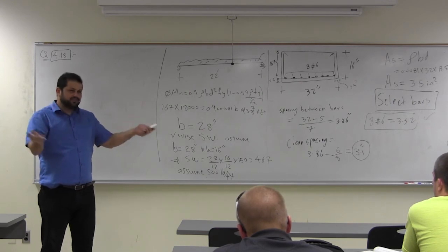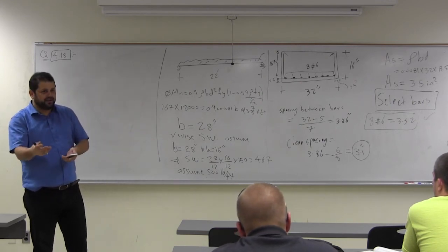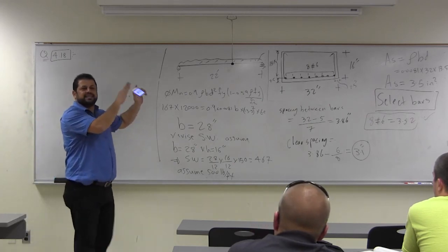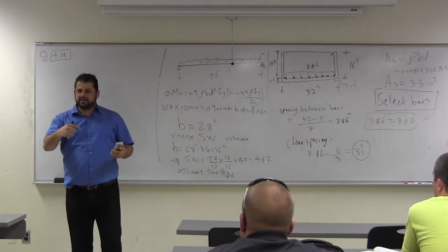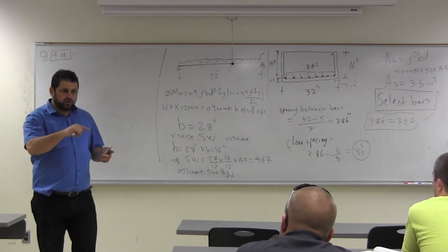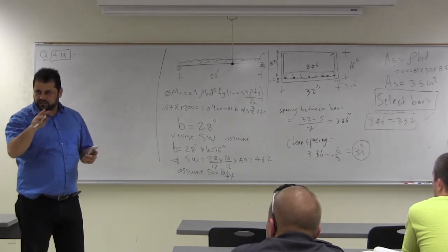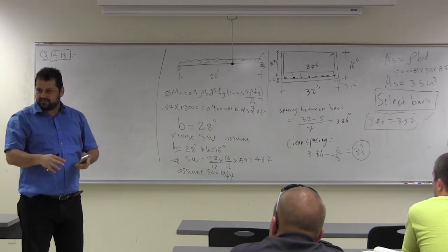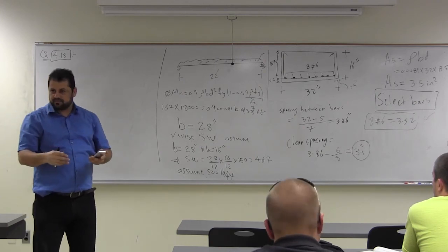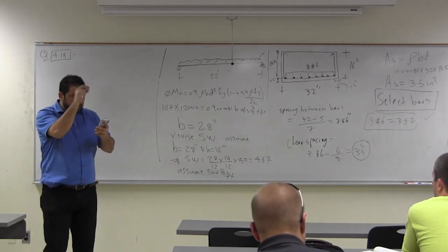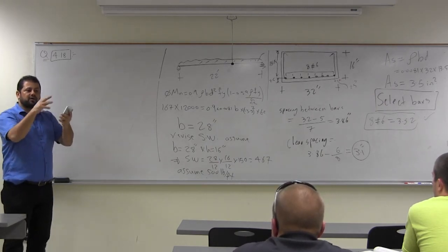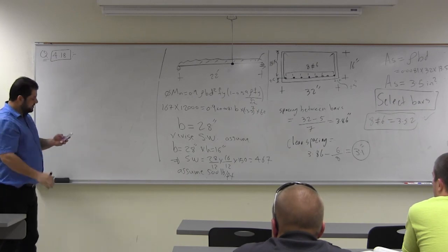What to assume, as I told you, 200, 300, 400, we're not selling gold. You don't have to get it exactly. And when the question tells you to design so that rho equals 0.006, rho 0.005, it doesn't have to be exactly, unless it tells you, I want exactly that number. Within that range. Don't try to make it exactly that, you cannot. You would find the steel that will give you around that number. Okay?